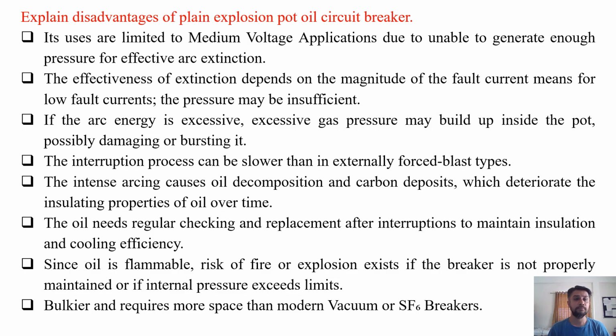Some of its uses are limited to medium voltage applications due to being unable to generate enough pressure for effective arc extinction. The effectiveness of extinction depends on the magnitude of the fault current, meaning for low fault currents the pressure may be insufficient. If the arc energy is excessive, gas pressure may build up inside the pot, possibly damaging it or bursting it.